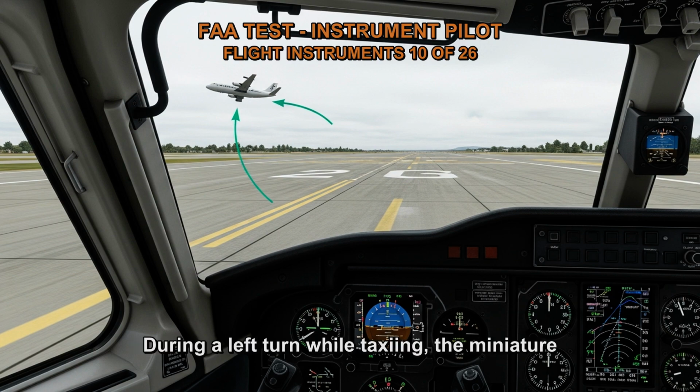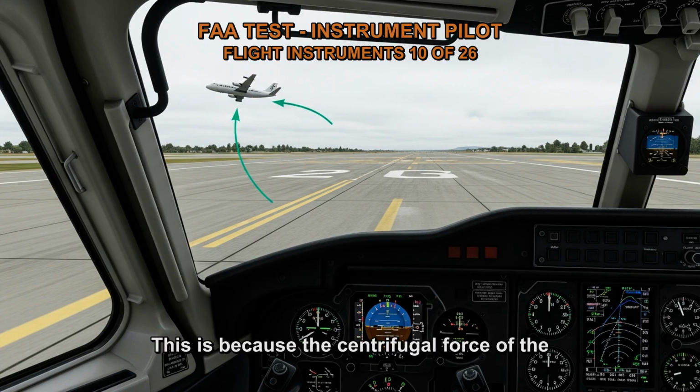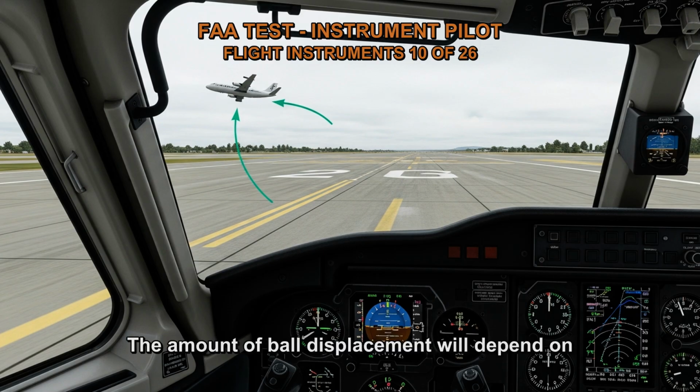During a left turn while taxiing, the miniature aircraft will show a turn to the left and the ball will move to the right. This is because the centrifugal force of the turn is pushing the ball to the right. The amount of ball displacement will depend on the rate of turn.